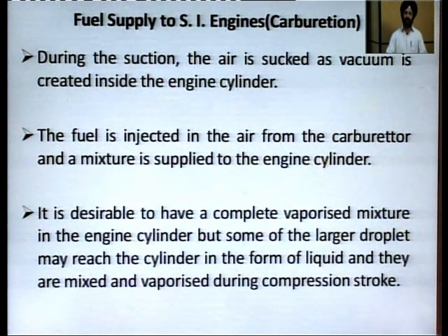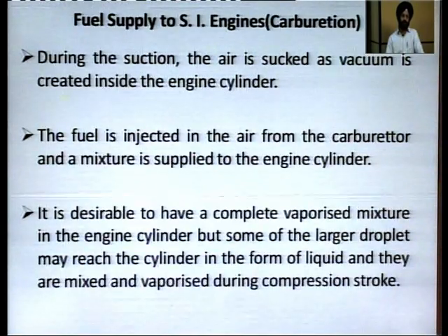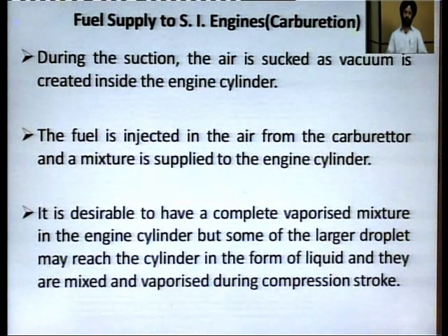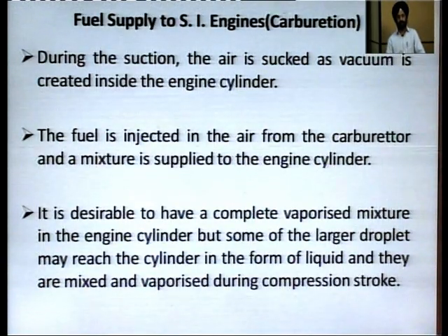It is desirable to have a completely vaporized mixture, to have complete combustion of the fuel and use its whole chemical energy. We must completely vaporize the mixture before we supply it to the engine cylinder, but some of the larger droplets may reach it. Atomization may not be proper. Then some droplets may reach the cylinder in liquid form, and they are mixed and vaporized during the compression stroke.